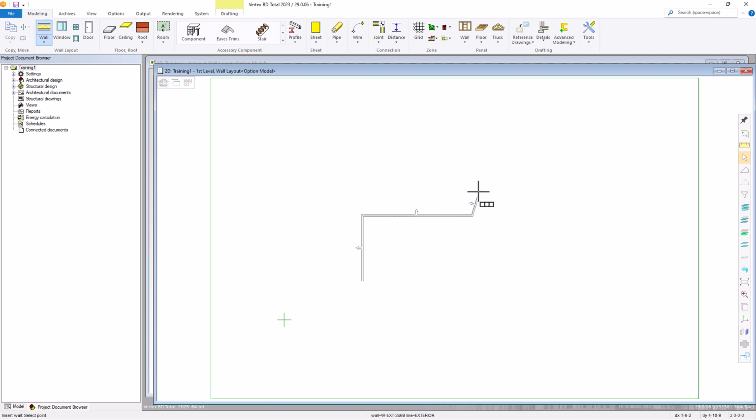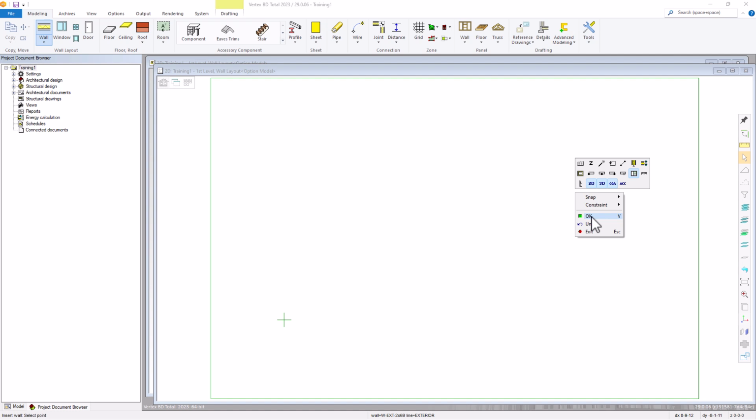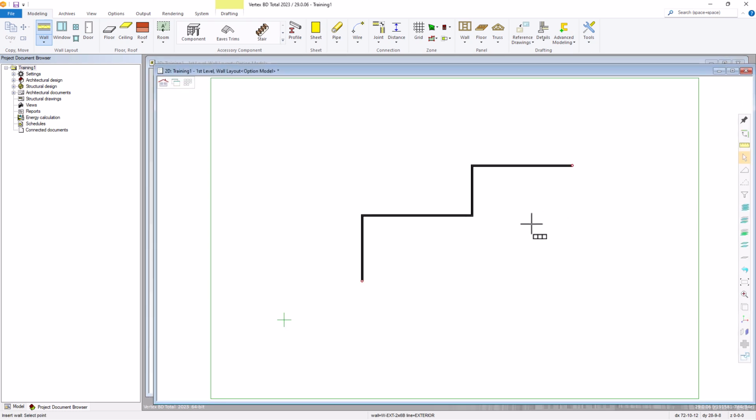Now, as I'm drawing a wall, each one of these walls has all those settings applied to it. So I'm going to hit V to confirm. So I can go through and select a wall and edit the framing tools for that specific wall. Right now, all of these walls that I have drawn have the exact same tools applied to them, but maybe you have a wall that requires a different type of framing. Maybe there's more loading applied. Maybe you need a different stud on center spacing to handle the loading, or some other aspect that needs to be modified.